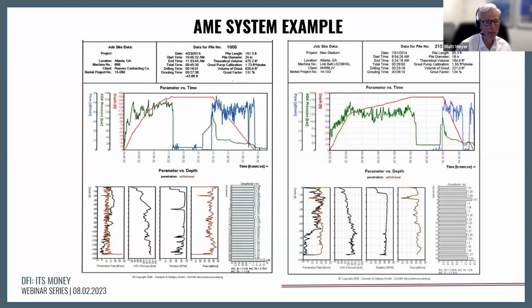So these are very critical to our verification of those concepts I mentioned, the type 2 concepts specifically, where we're encountering that intermediate geomaterial, we're drilling sufficiently into it, and the intermediate geomaterial is of sufficient hardness, or we're inferring it's of sufficient consistency so that it's similar to our test pile conditions.